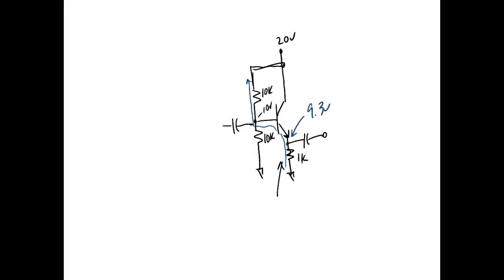So I come in here, I can put a lot of voltage in on this thing. Let's say I put 4 volts peak to peak. What would be my output voltage? We've already taken out the 0.7 of a volt. The transistor's turned on. And this is called an emitter follower. Why is it called an emitter follower? Because the emitter is following the base.